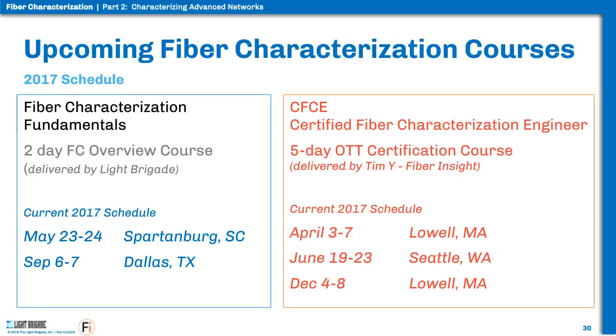Or it could just be, we were talking about this today in class, a shift. So let's say I've got a fiber link and I'm handing off to another carrier, or maybe somebody I bought fiber from, and the rest of the link is G655 where my section is G652. You'll see a gain in one direction, but if you shoot from the other direction back, you'll see a loss that's greater than the gain.